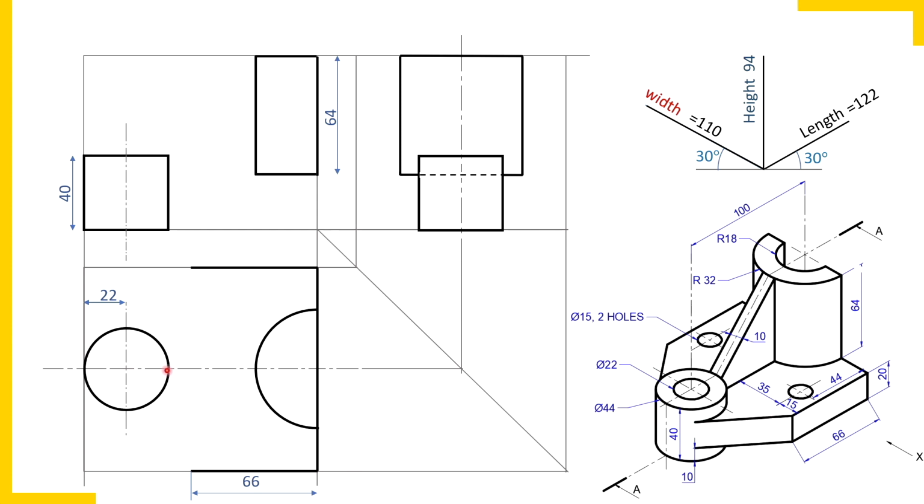to the cylindrical surface. So here is the cylindrical surface that appears as a circle in the top view. So simply draw tangents. So manage two tangents from the ends of these two principal edges, and this is how that plate is complete in the top view. The remaining two views are rectangles, simple. So from end projectors. So watch here, this is the shape of the plate in the top view. The boundary of that surface I am showing you. This is that.